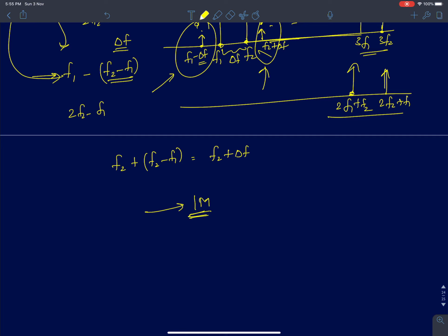Here two carriers are very close to your desired signal of interest. So your desired signal can be F0, and you can have two carriers F1 and F2. When they are fed to a nonlinear system, they can create a component at the frequency F0, which is delta F away from this, and this separation is also delta F. So these two signals can intermodulate and create a component. We'll see what is the magnitude of the components that we'll be receiving.